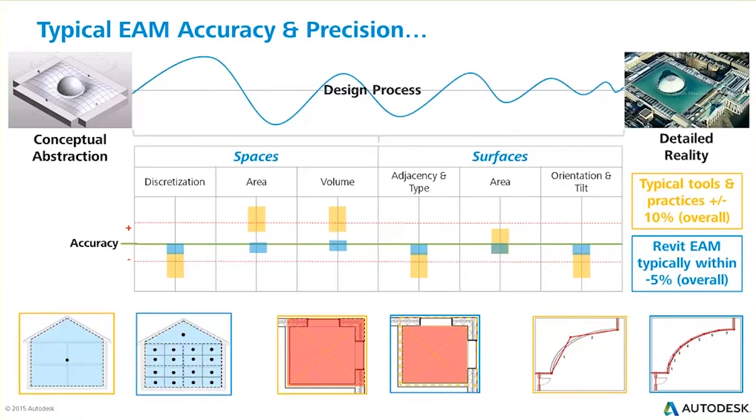So on average, the Revit model is within about 5%, and that's for a detailed model. It's directly proportional to how accurate or how clean your model is. And what's important, if you do this workflow from an earlier stage, you'll see that by the time you get through this process, you're typically more like 1 or 2%, and you're just into the state of noise then. It just doesn't matter anymore. So very, very accurate and also extremely quick. It takes anything from a couple of minutes to maybe a morning for a very detailed model that you're starting energy analysis on for the first time, as opposed to a few weeks for doing something like that.